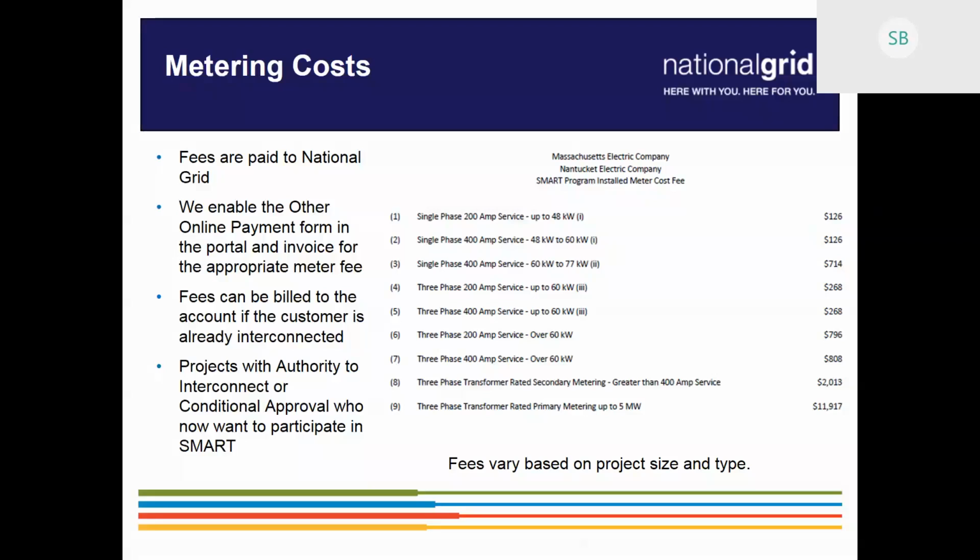Could you please talk a little bit about inverter derating and how you view that and what's acceptable and what you expect from one line? Yeah, so inverter derating, like if you have a standard 1 megawatt inverter, but you want to derate it down to, say, 750, whatever it might be, because that's what works for your site. We do allow derating of the inverters. It has to come straight from the inverter manufacturer and has to be